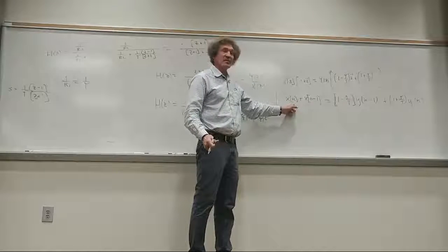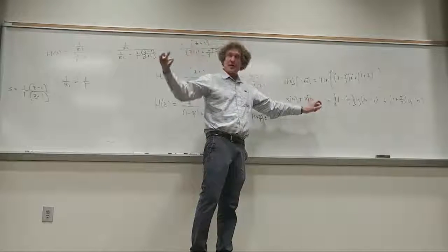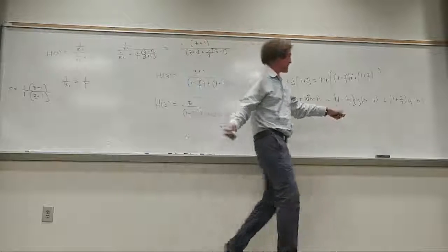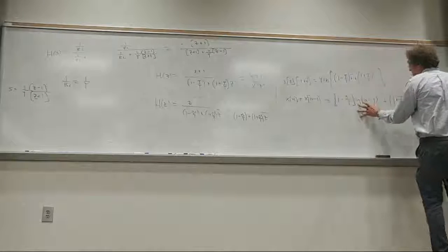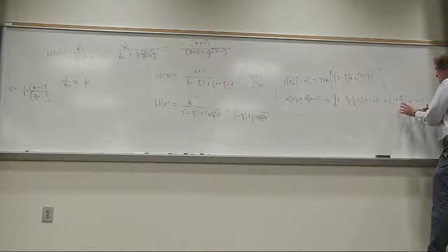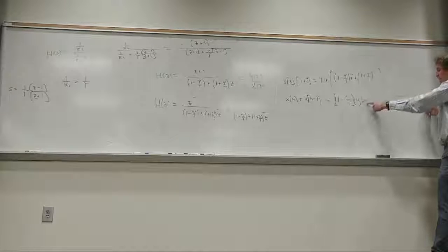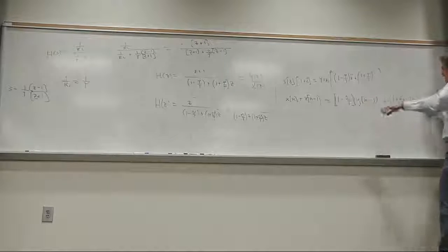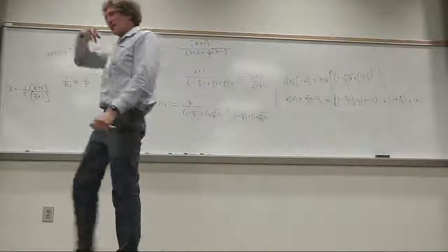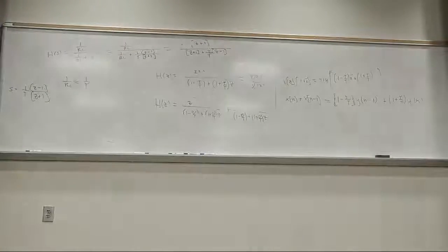You take the value of a sample, you store the value of the sample minus 1, and you add the two together, right? That's equal to this, and what happens? This y of n minus 1 goes on that side with that coefficient, and you get y of n from the previous value of y, and of course you have to divide that by 1 plus tau over T. But you all see how now you've got a continuous time filter that you're very familiar with.